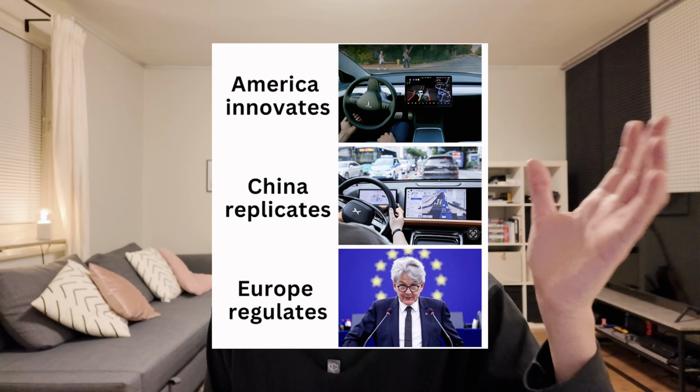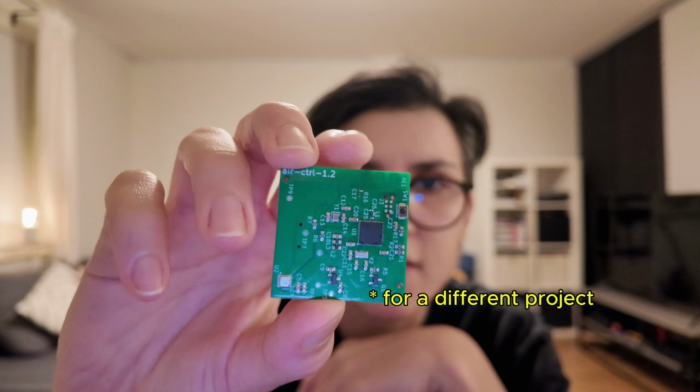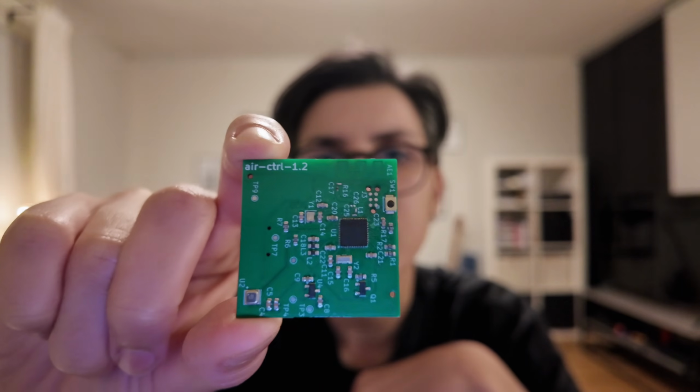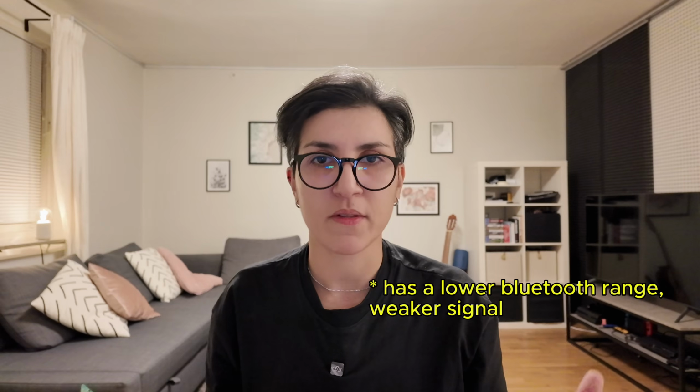And since we're using Bluetooth, the EU has the Radio Equipment Directive, and you need to be compliant with this directive if you want to sell your product in the EU, which of course I want to. So here, instead of doing my own design, which I by the way did before, this here is the first PCB that I designed. And if you see here in the top right, it has a PCB antenna. And it works. I could connect this to my phone via Bluetooth, but my design is suboptimal. So for the sake of making my life easier, making the certification easier, I'm gonna buy a module.